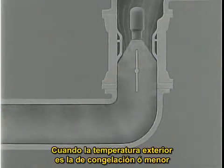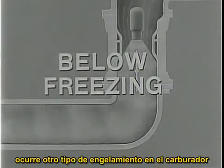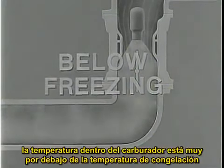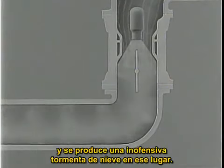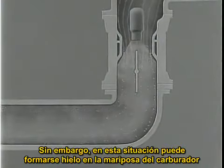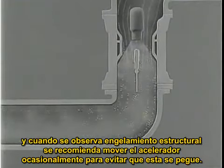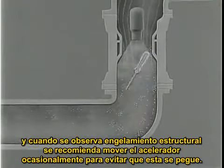When the outside air temperature is at or below freezing, a different icing condition occurs in the carburetor. The temperature inside the carburetor is well below freezing, and there is, in effect, a harmless snowstorm taking place. However, in this situation, ice may still form on the throttle, and it is advisable whenever structural icing is encountered to move the throttle occasionally to keep it from sticking.